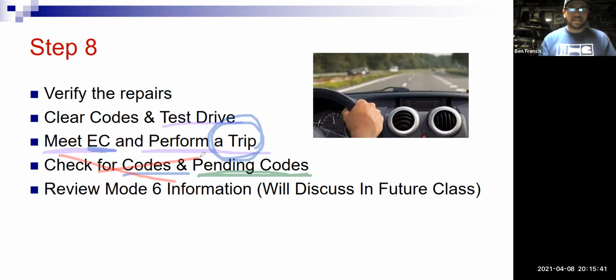And so all that stuff that we looked at on that chart, where the intake air temperature and the coolant temp weren't more than 40 degrees apart. The coolant temperature was less than 90. The airflow was less than 20%. So anyways, do all that. Then if there's no codes or pending codes, you're looking good.